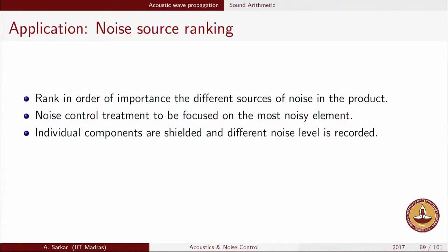We have something called noise absorbers, which are like fibrous materials. So, if each of these noise sources are covered with these absorbers, it is expected that the noise emanated from these machines will substantially reduce. But then you cannot sell a vehicle where your engine as well as the gearbox and everything gets cladded with these fibrous materials, because usually the longevity of this fibrous material is not very high. So, especially because of the temperature effects and the dust effects, they tend to get spoiled. The ones which are more reliable and more durable are extremely costly.